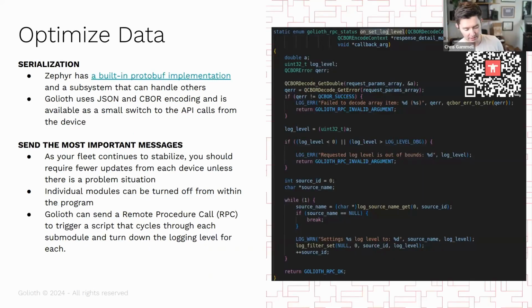In terms of data, I'm often thinking about this because I'm often doing cellular stuff, and data has a battery cost like we already talked about, but also an actual real cost when you're paying an MVNO or an MNO. So you might want to be cutting down on your data as well, especially as you start to scale your fleet, right? If your data costs 50 cents per device per day or something like that, and you have 1,000 devices in the field, every incremental cent basically starts to give you an extra $10. And that scales with the number of devices you actually have in the field.